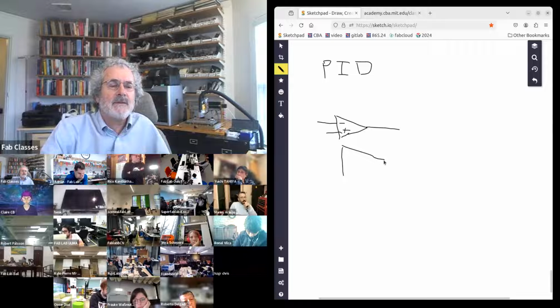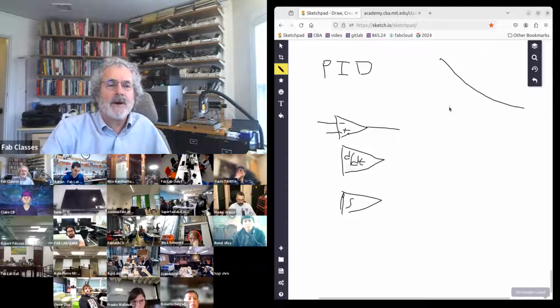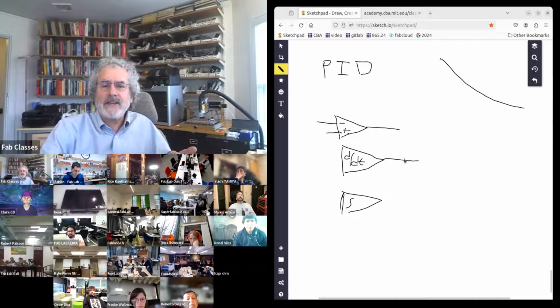But we can, in addition, do two more things. And I'll write this mathematically, but you don't need to know how to do calculus. This is a derivative. This is an integral. Just the error term means you have a big control when you start. You slam it on. The derivative term measures the rate of change, and it prevents you from moving too quickly.